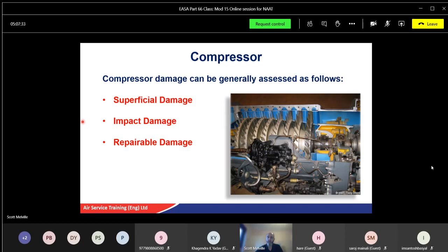Superficial damage, in the form of small dents, may be acceptable provided it does not form a pattern all together. Now you get a lot of superficial damage on the back of a compressor blade, where the air is obviously hitting the front, but it stagnates a bit behind it, and you get small indentations, which is normal. That's just standard on any one. It's the big indentations you're looking for, providing there's no evidence of too deep and too much, which can cause a crack. Any damage is a potential to cause a crack. Yeah. The limits for dents and blends will be in the manufacturer's manual.